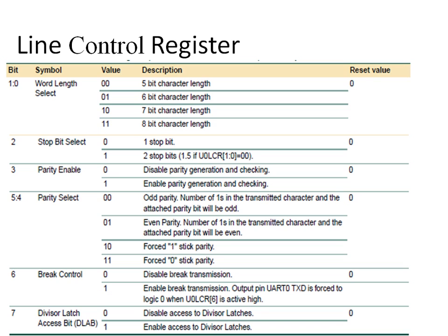So what do you mean by word in case of LPC2148? Word is nothing but 32 bits. Okay, but we represent a single character by using 8 bits. So it means it differentiates every 4 characters when it is programmed to 1. So if you are making it 1, then every 4 characters are differentiated.